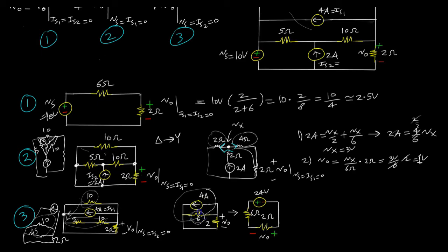Remember that the resistor remains the same, 6 ohms. The voltage becomes 6 times 4, which is 24. And just remember that you can drag this guy, kind of bring it down here, but keep track of the signs. You get a minus and a plus in this manner. You can do a voltage divider. It's kind of funky looking, kind of on its side, but that's no problem.